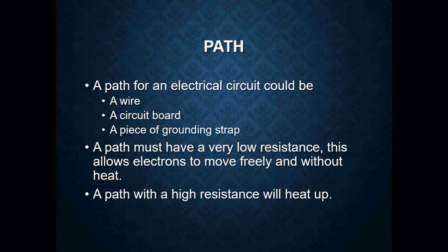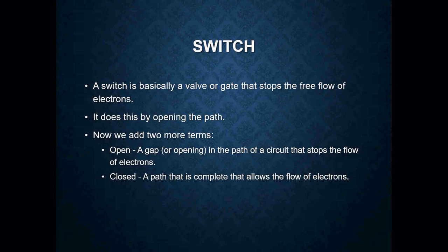So when we look at electrical wiring in HVAC equipment, we want to look at the wires. We want to look at the insulation around those wires. Are they heating up? Did they melt? Do they have any signs of cracking, missing insulation, any sort of deterioration? Because if so, there's a chance that those wires are heating up too much and we have a problem with the electrical flow going through those wires, because maybe the wire just has too much resistance. It could be the wrong size.